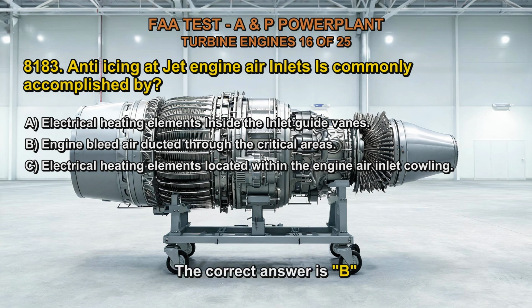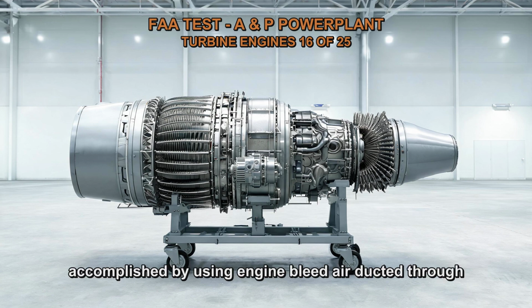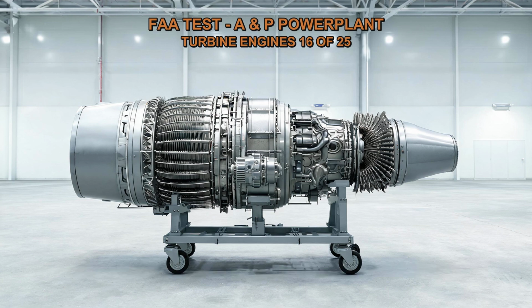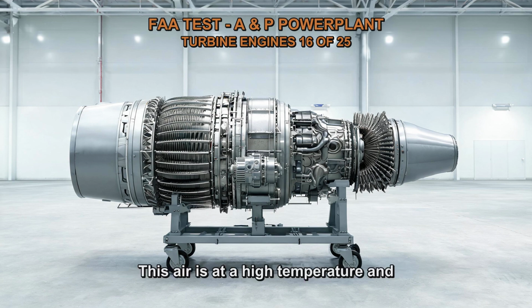The correct answer is B. Anti-icing at jet engine air inlets is commonly accomplished by using engine bleed air duct through the critical areas. Engine bleed air refers to the compressed air taken from the engine compressor stage. This air is at a high temperature and pressure. By ducting this bleed air to the critical areas of the engine air inlets, it can be used to prevent